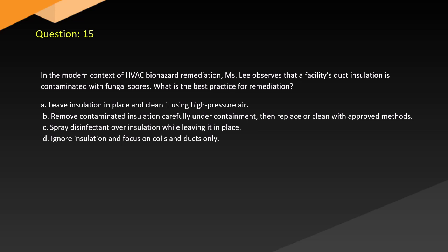Question 15. In the modern context of HVAC biohazard remediation, Isley observes that a facility's duct insulation is contaminated with fungal spores. What is the best practice for remediation? A. Leave insulation in place and clean it using high-pressure air. B. Remove contaminated insulation carefully under containment, then replace or clean with approved methods. C. Spray disinfectant over insulation while leaving it in place. D. Ignore insulation and focus on coils and ducts only.